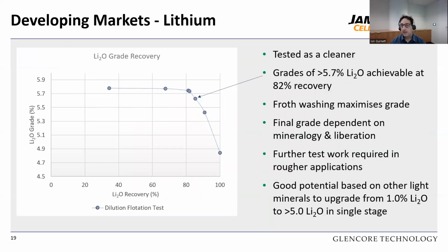Lithium is another thing that we've been seeing a lot of interest of late, and I put a dilution flotation test here just to show you what some of the stuff has been capable. And here we ran lithium as a cleaner. We found that we could achieve about 5.7% lithium oxide grades, around 82% recovery.